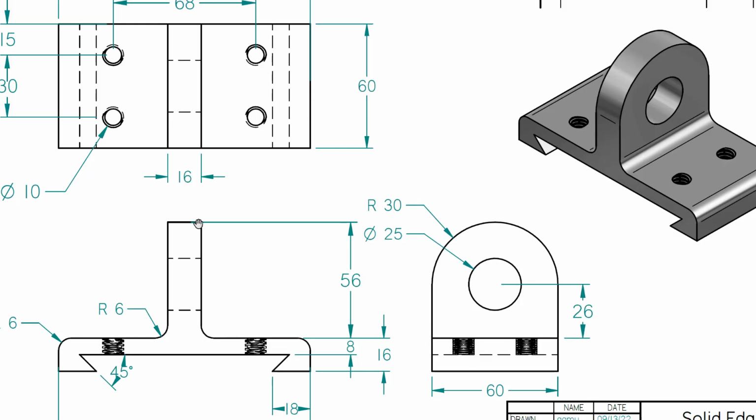The dimension looks fine. The next step is I need to draw the other shape here. If you look carefully, this one is 16 wide and the height is 56. There are many ways of doing that. The way I prefer, I'm going to draw a rectangle by center, make the width 16 and the height 56, and make it aligned with the center line here, and then we can fix the location to be tangent to the edge here.